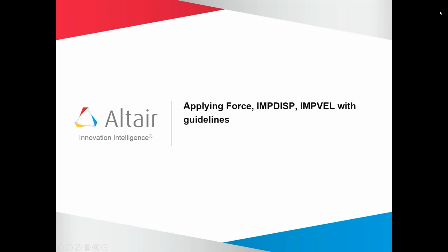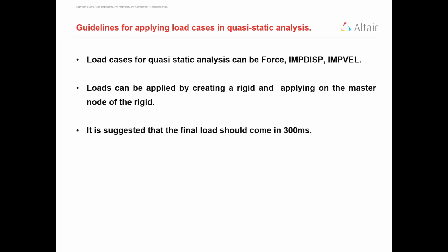The topic of this session is applying force, imposed displacement and imposed velocity in Radioss. The main objective is to demonstrate how to apply loads in quasi-static analysis. There are some guidelines to be followed here. They are: the load cases for a quasi-static analysis can be a force, an imposed displacement, or an imposed velocity.